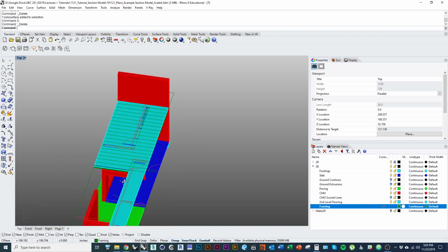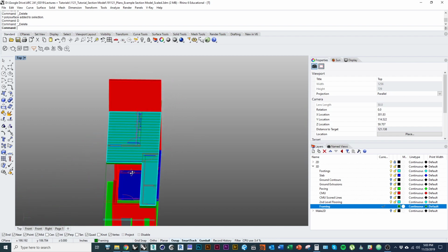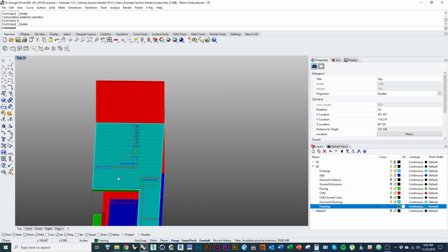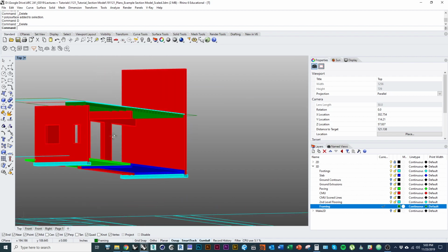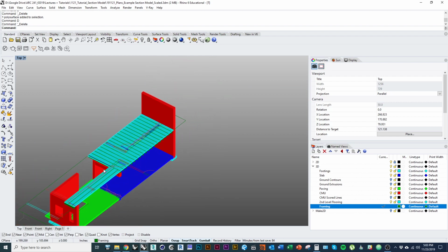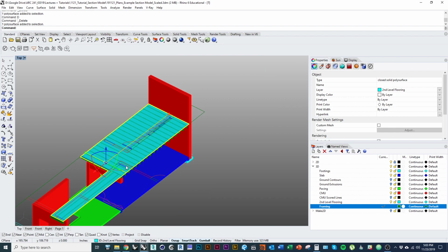So what I'm going to do, I think, is basically just leave this half exposed and clad this half in this direction, just so we have something simpler, where we'll see part of the framing here, part of the roof framing of this volume, and that window frame, and then everything else can be clad. So what I'll do right now is select this surface and use the command cut plane.